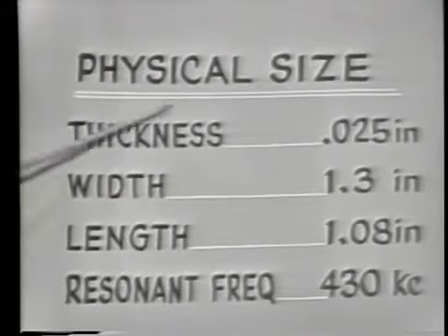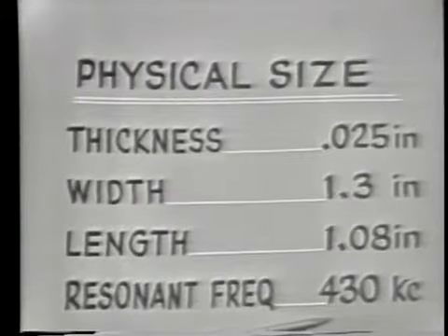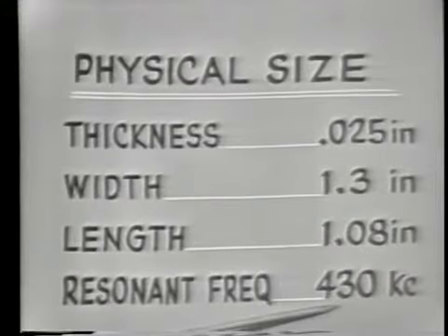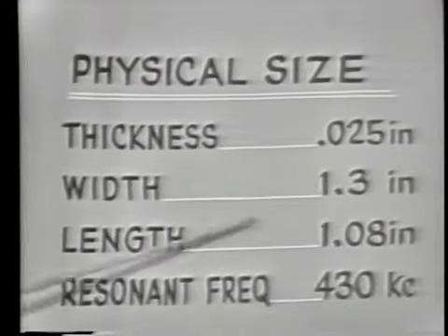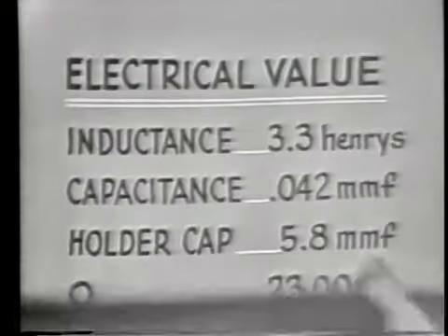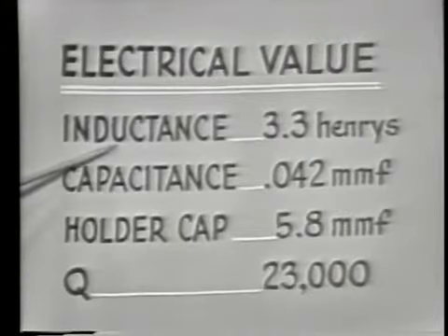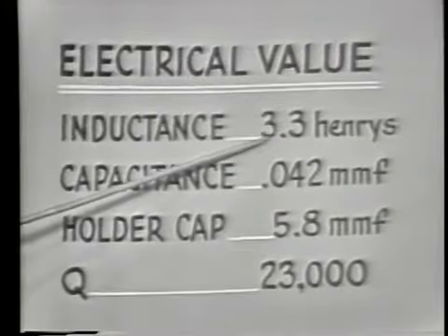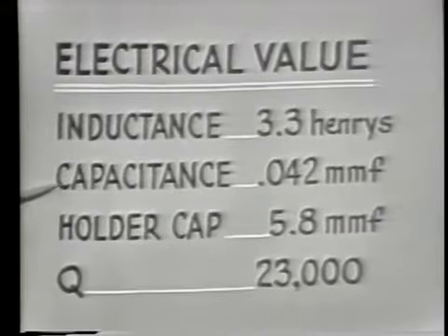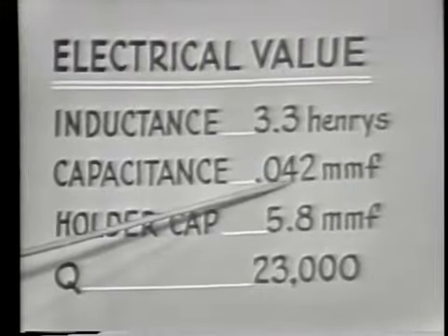And with these physical characteristics, the resonant frequency, or the fundamental frequency, would be 430 kilocycles. Now, with these physical dimensions, let's look at the electrical values. The vibrating crystal would have an inductance of about 3.3 henries, a capacitance of 0.042 microfarads.